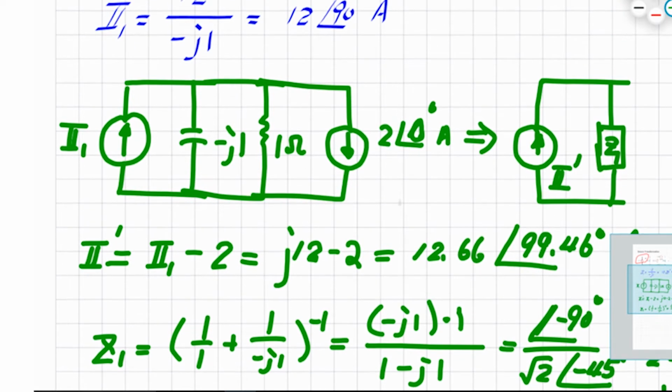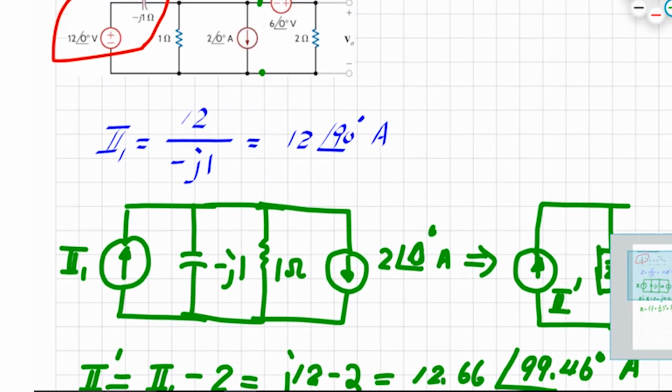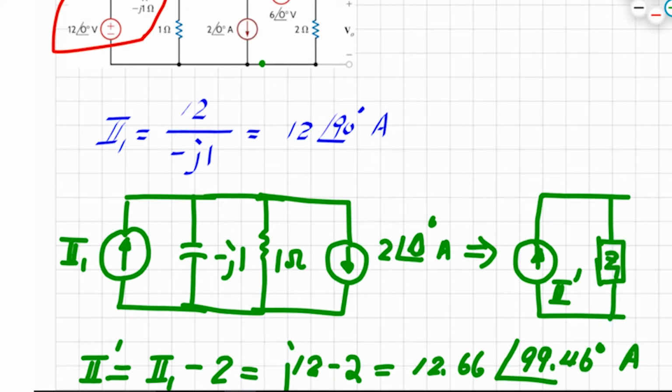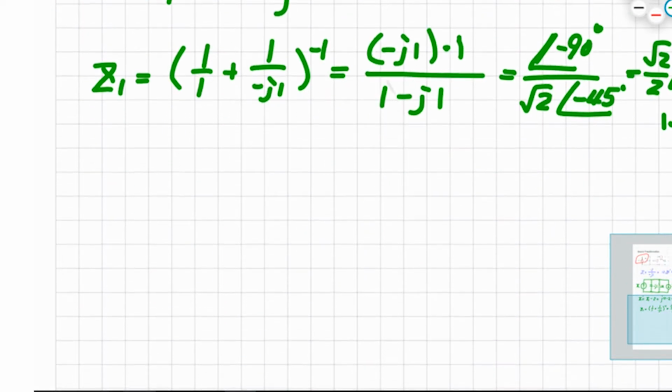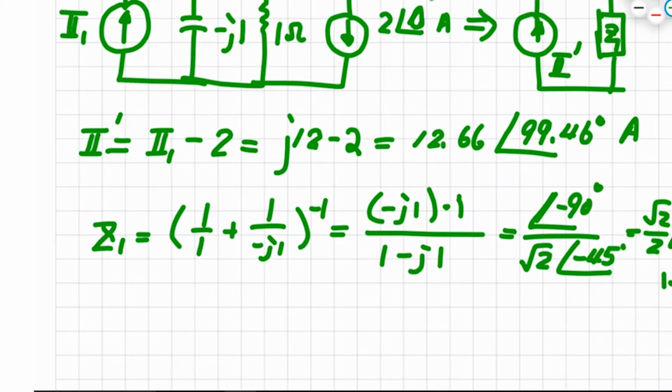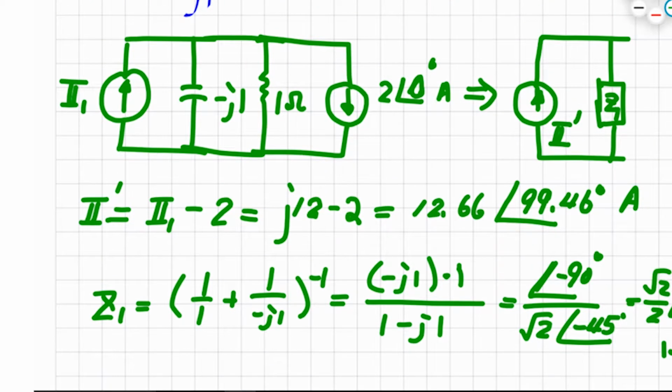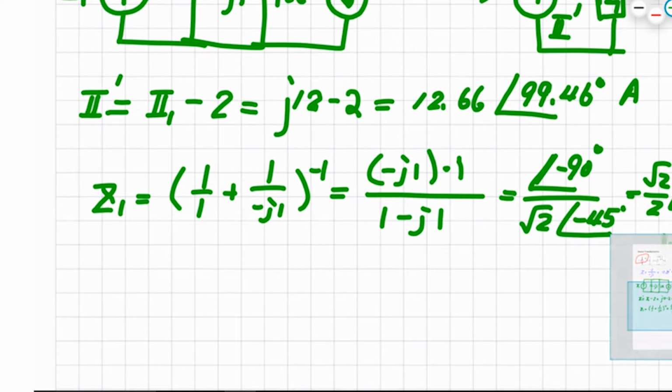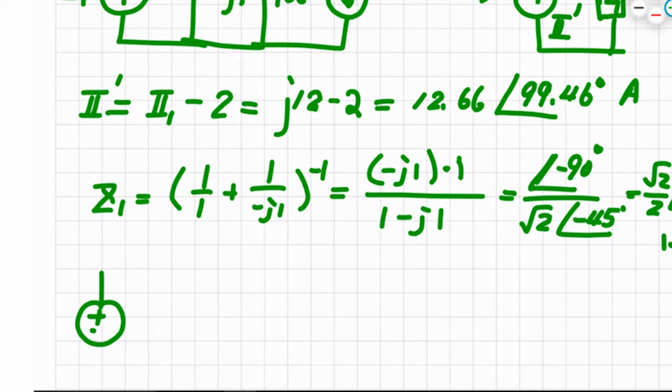So as we talked about earlier, once we have that combined up to that point here, there's A prime and B prime. And what we can do then is once again convert that back into a voltage source, because we wanted to combine it with this second voltage source there.